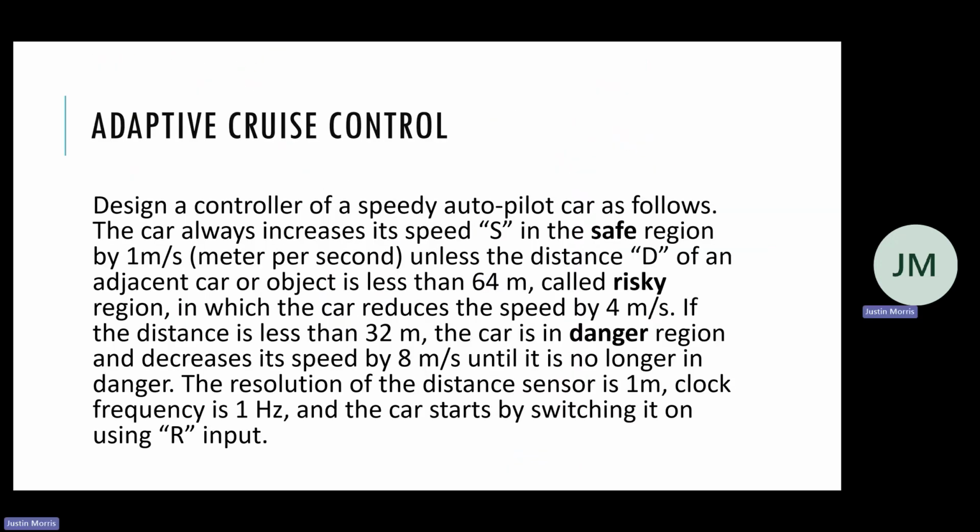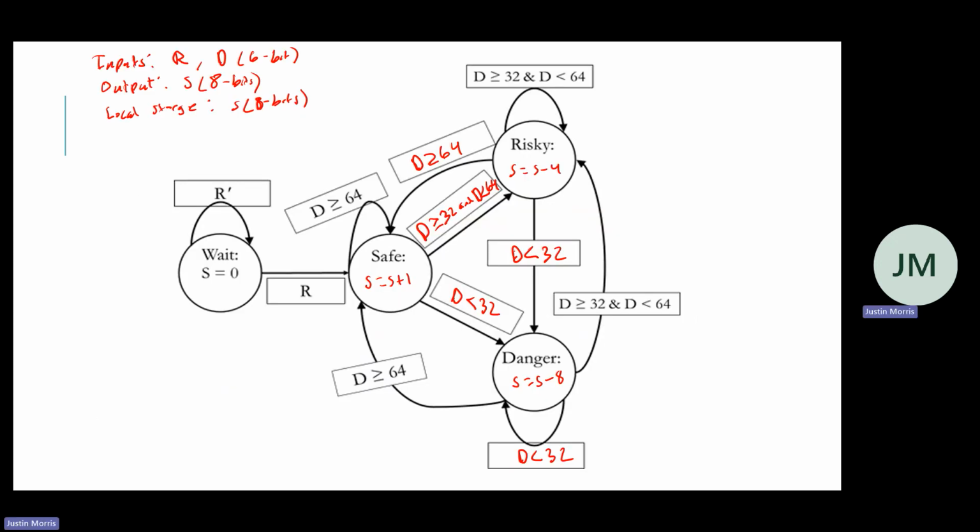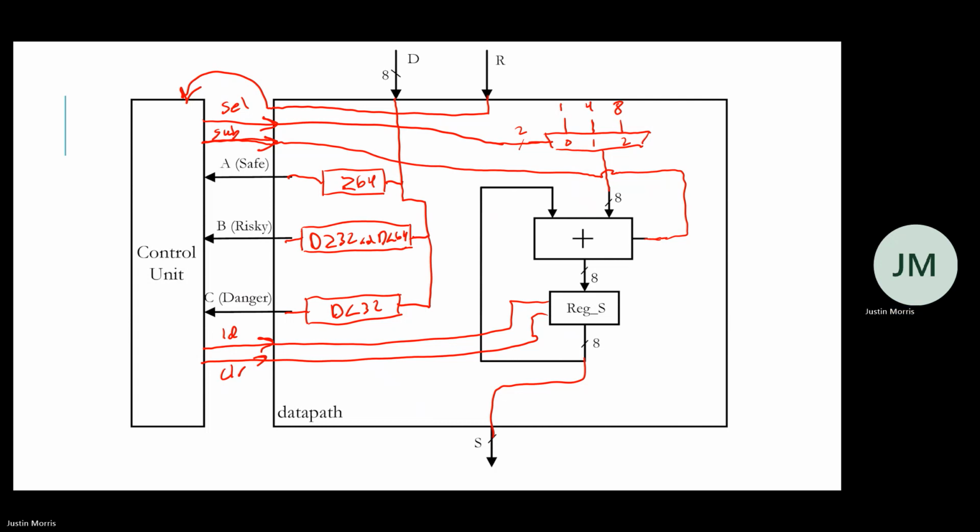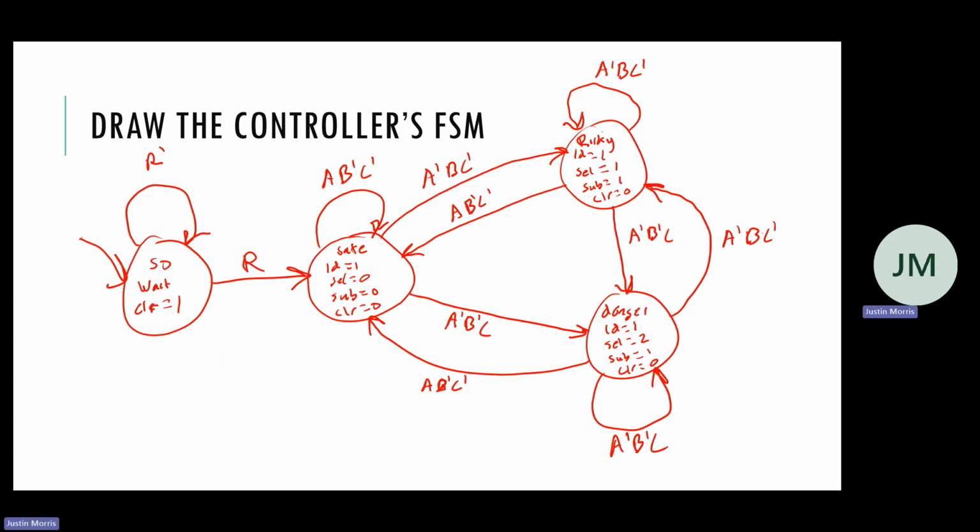We have the description, high level state machine, data path, as well as the connection between the data path and the controller, and the finite state machine implementing the controller. Right? These are all of our steps. From the memory lab, we know how to now make this into VHDL. Right? How many files for the controller? 1 plus maybe a test bench.